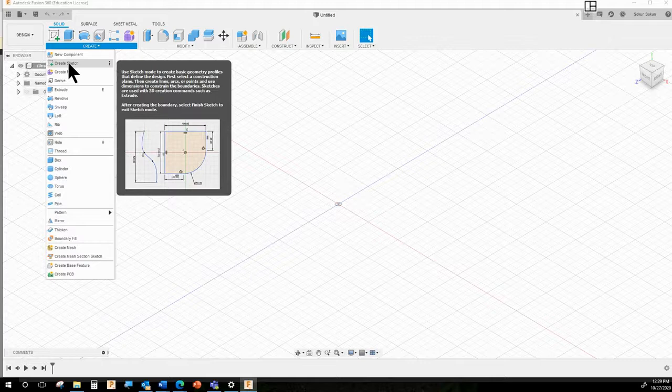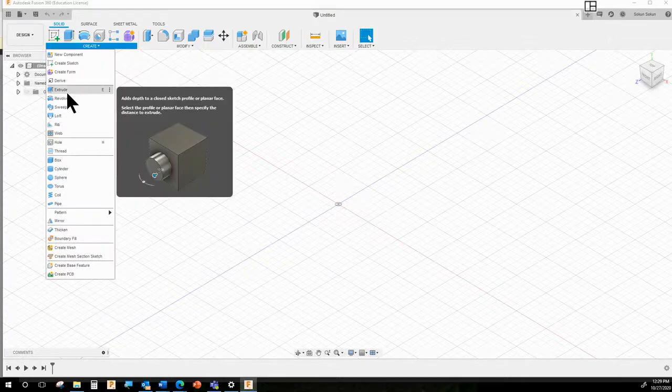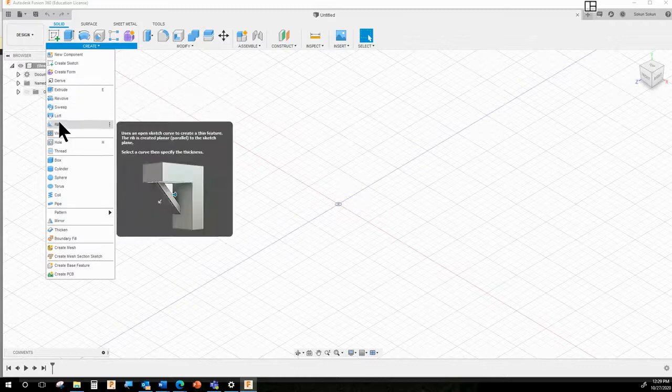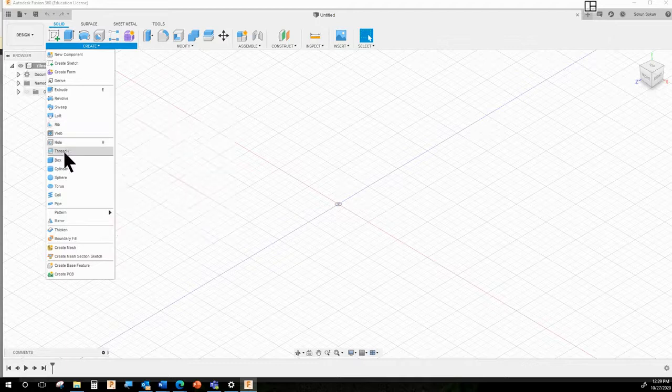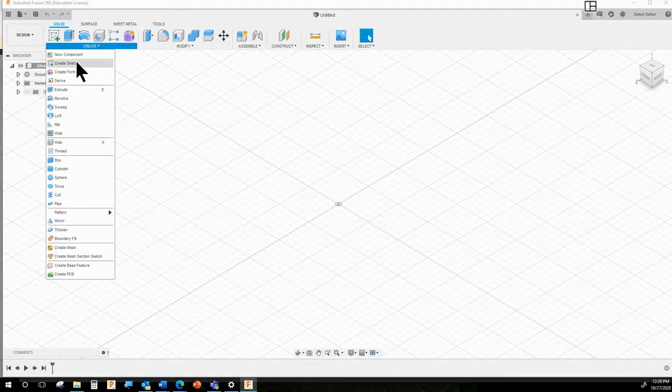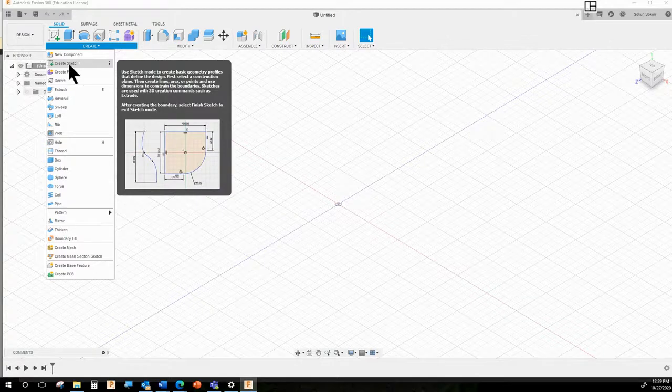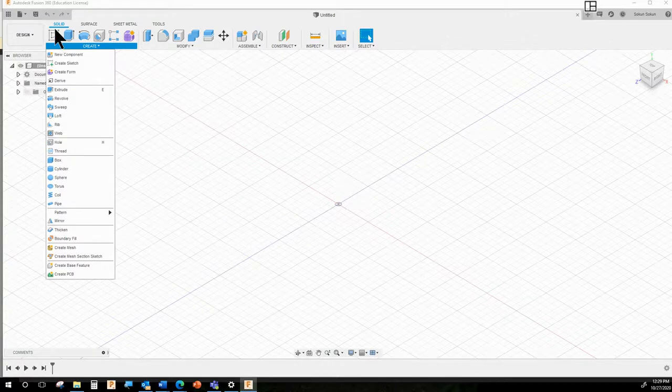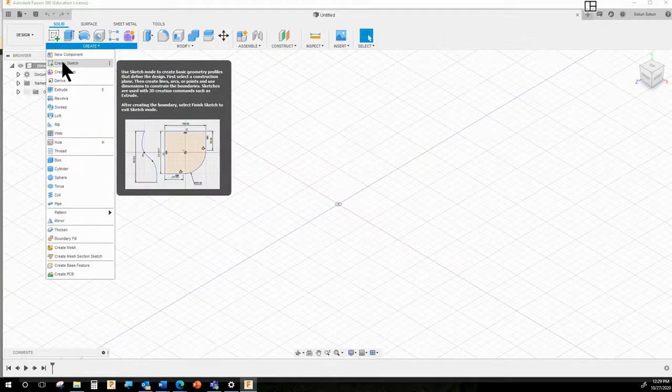And one of the things here is also Create Sketch. Once you've created this sketch, then you can extrude, revolve, sweep, loft, rib in order to turn it into a three-dimensional object. This other stuff comes up here and there. These are little shortcuts that I wouldn't worry about because I think they're just kind of dumb, and I don't really see the use to them. So for almost all purposes, the first thing you're going to do anytime you're starting a design is sketch it out.